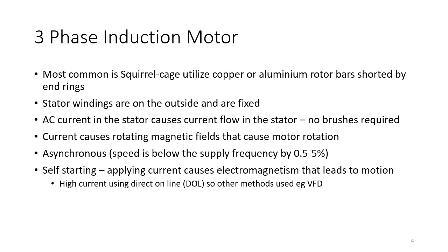Direct online is where you apply electricity directly onto the motor via a contactor with no other mechanisms. The high current can be offset by using other methods such as a VFD or a soft starter, or there's also the possibility to use older techniques such as star and delta type starters, which can reduce the initial high starting current.